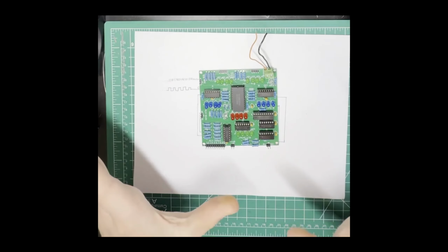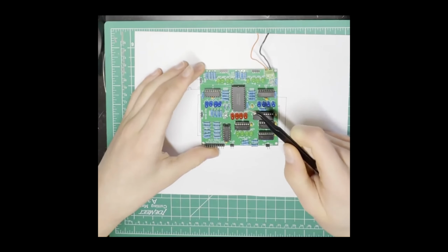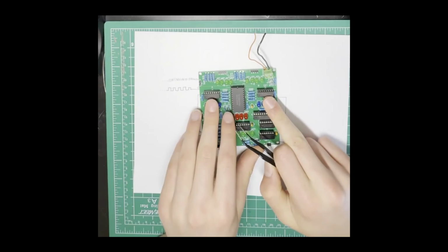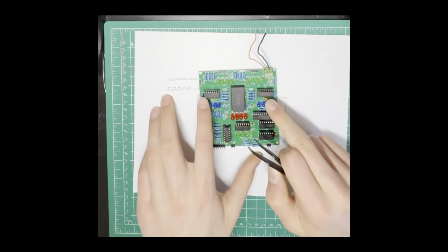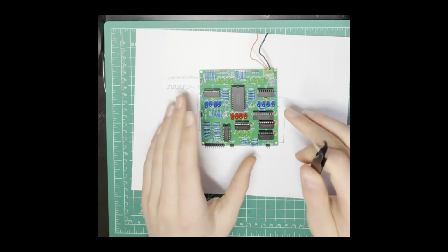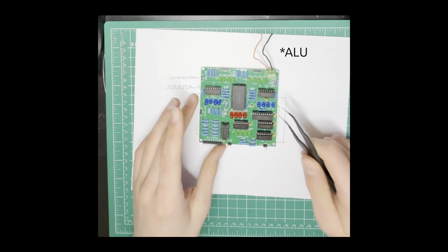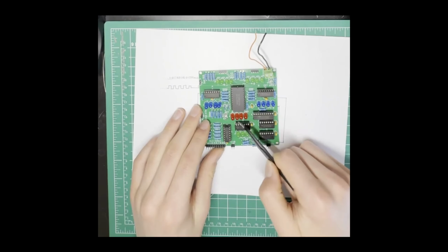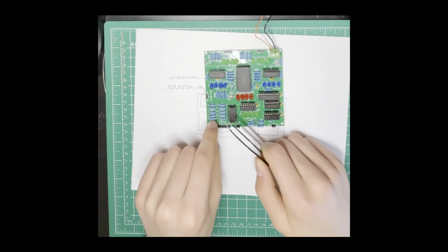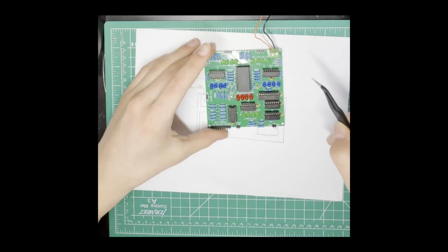The CPU consists of around 2 to 3 parts. The ALU itself, this is a 74LS181. This is the heart of it, so it can do comparison operations, arithmetic, and logical operations. And then you have our A and your B registers right here. And in this scenario, this is actually RAM, not registers. So this was slightly more complex, but just for the sake of education, these are registers here. So we have A and B registers that feed into the ALU. That output then gets fed into this ALU out, which feeds into another register here. That register then goes out and gets buffered onto the bus, the shared bus.